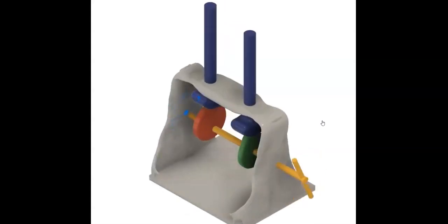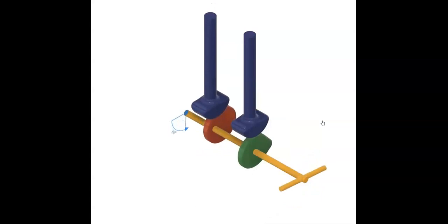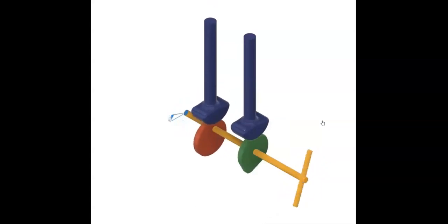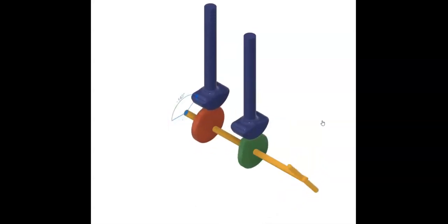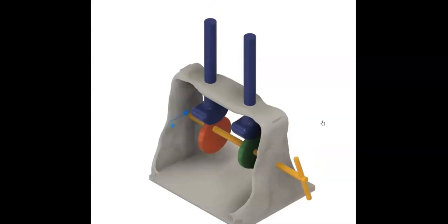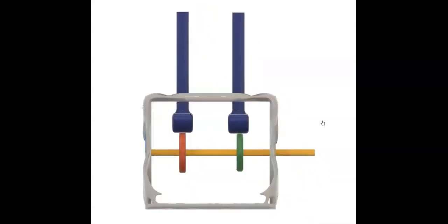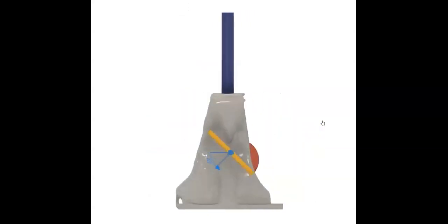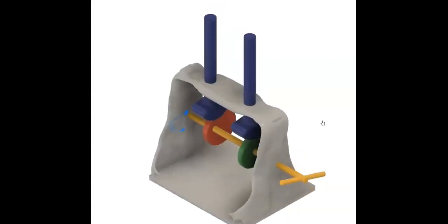The whole entire point of an automata box is telling a story of what happens when a crankshaft is rotating and how those cams behave. You're trying to get the blue followers that you see here to go up and down. And we're trying to be able to read a chart and say, based upon where we want the follower to be, we can change the cam to tell the follower what to do. It's rotational motion to vertical linear motion. That's what we're learning in class.